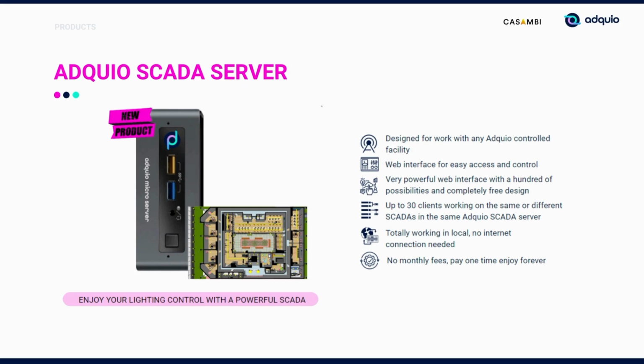It uses a web interface to display SCADAs, therefore you will only need a web browser to be able to enjoy all the content of these SCADAs. You will see that you can design any type of object, circles, squares, or any other type of figure. You can upload your own objects too. Above all, you can make these objects dynamic by connecting them to the variables of your devices. For example, you can change the color based on the content of a variable. You can change their position.